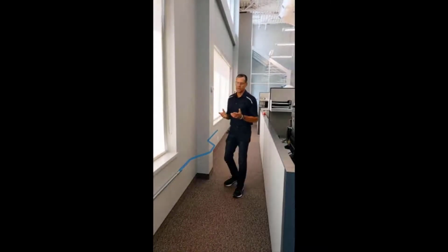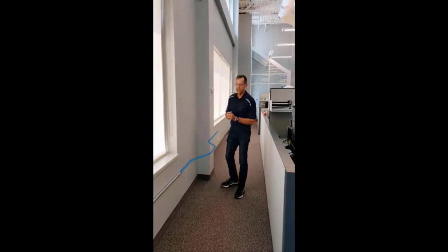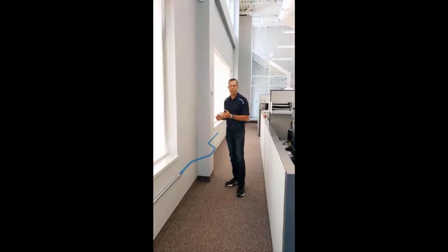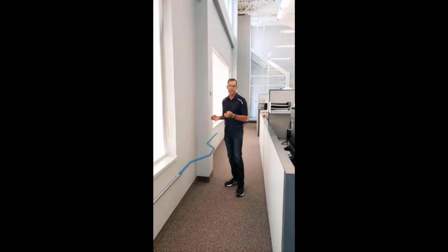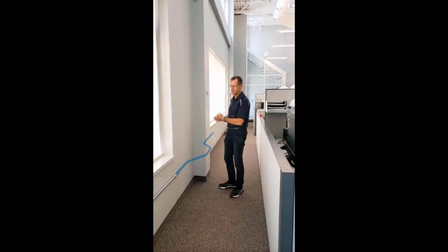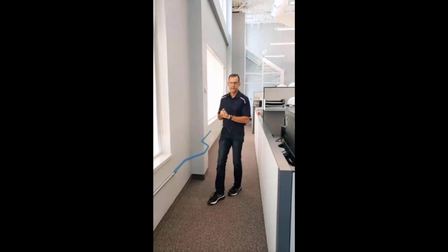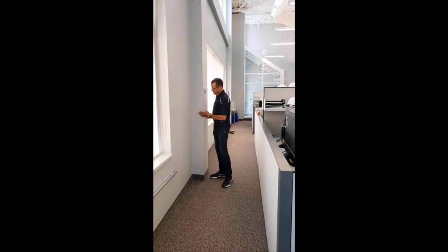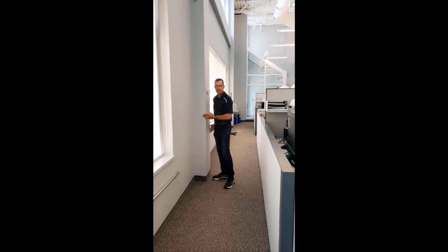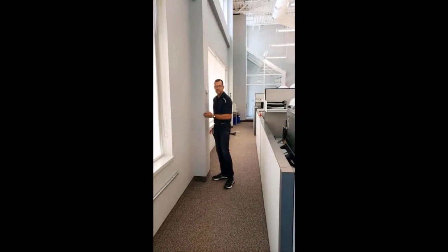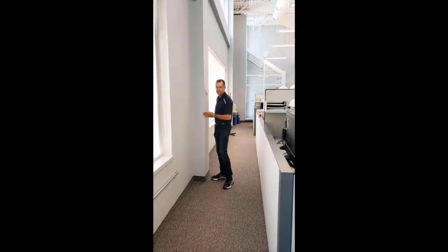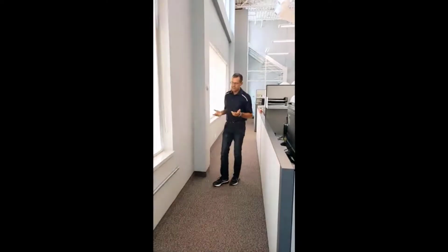So there are a couple of ways to do this. Conventionally, we would have to do some math to figure out where our bend marks are going to be on our conduit in order for us to properly bend the conduit and for it to fit. The particular obstacle that I'm trying to go around, my 4-point offset, is 8.5 inches deep by 13 3/4 inches wide. So we'd have to do a little bit of math.